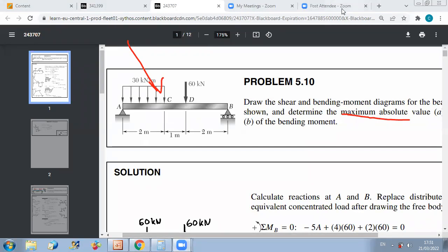So as we discussed, first calculate the external reactions. Here, as we discussed, a pin can develop forces along Y and X. Since here the only type of forces is transverse forces, of course no AX. Okay, AX is 0 because we don't have any normal force acting on our beam. So we just have two unknowns, AY and BY. Now, as we discussed before, you have several ways to calculate AY, BY.